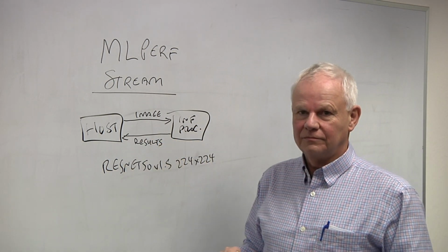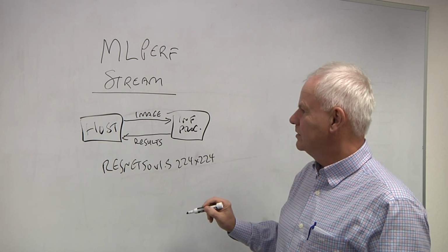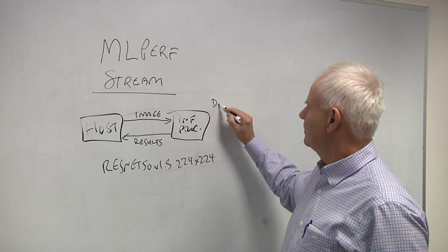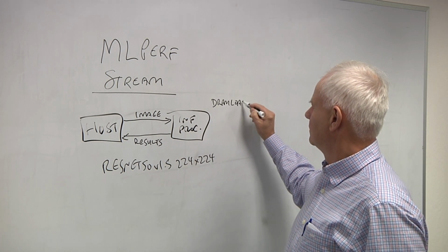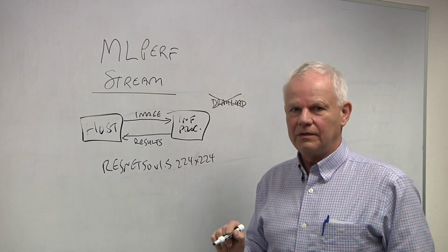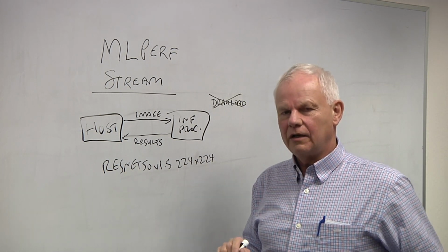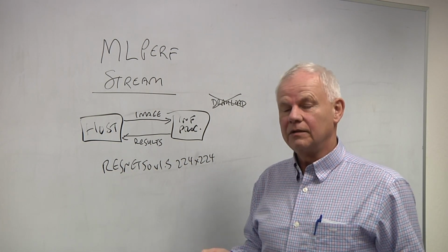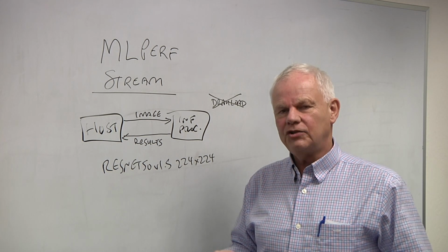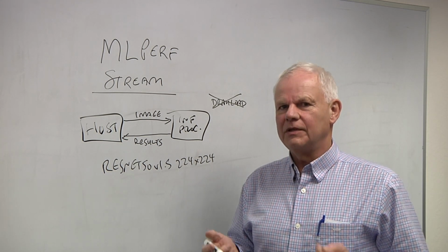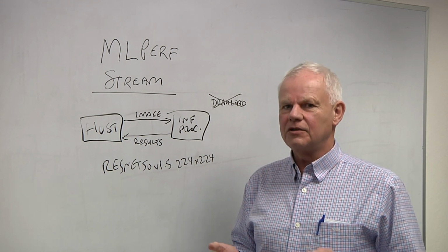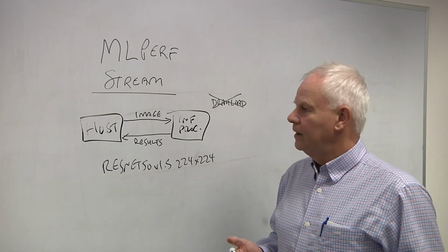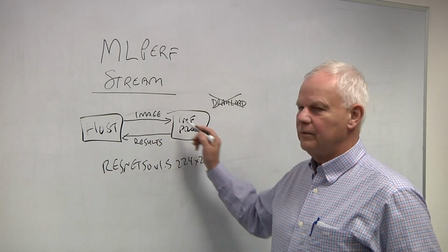And those caveats are what? Those caveats are, first, for whatever reason, the DRAM load time is not counted in the latency. Not clear why, because in a real system, the DRAM has to get loaded. Also, things like cache warm-up time is not included in the latency. It's not clear what that entails, and it'll depend on a processor. But it's 1 image at a time.